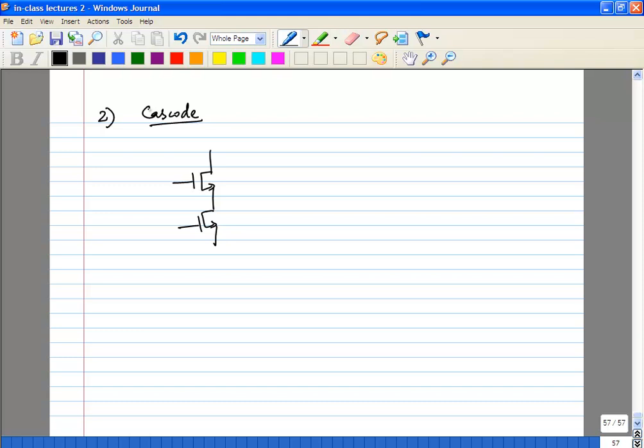Okay, so just remember that if you do this, quite often you might want a different size for the cascode. Your starting off size will be the same as your main transistor, but at the end of your optimization it may not be the same. You may not need a much larger transistor. Maybe you can make do with a smaller transistor. Maybe you want a larger length for the cascode, but the thing to keep in mind is you will have some parasitic capacitance at this node and you want to minimize that capacitance. Why? Because obviously your signal is going to get diverted through that.